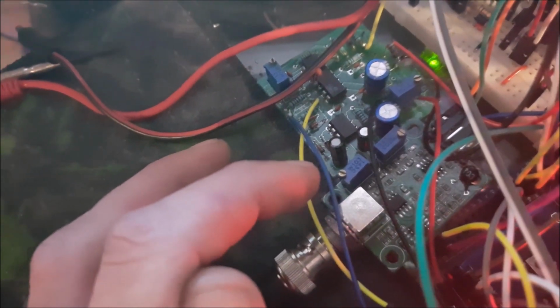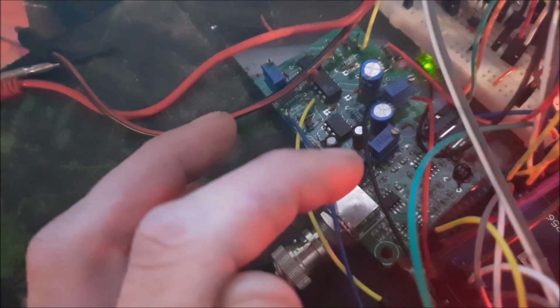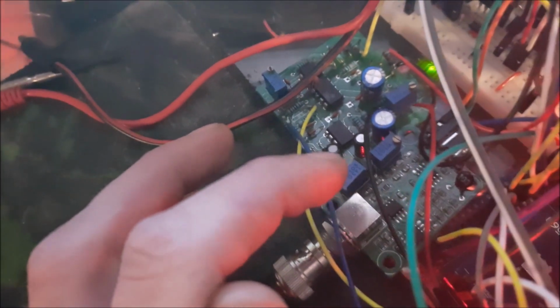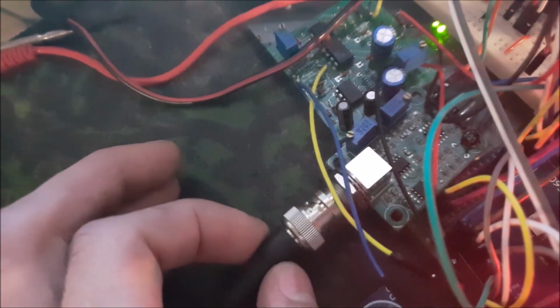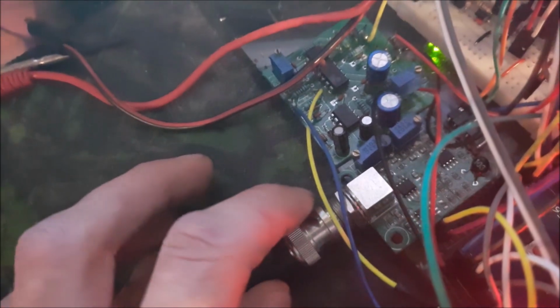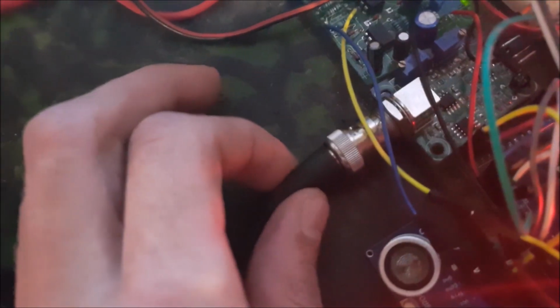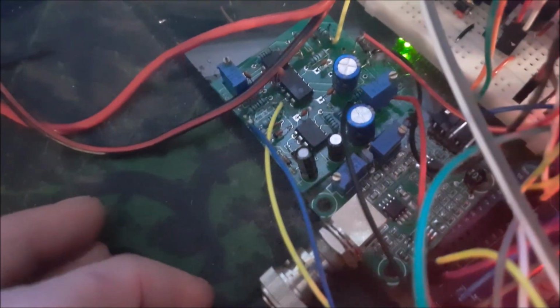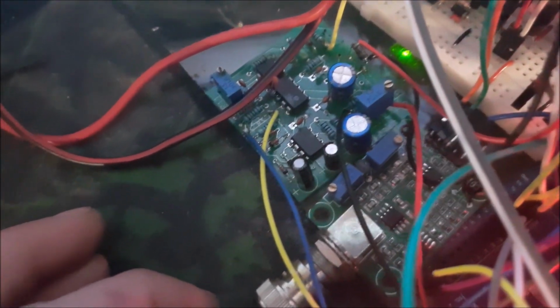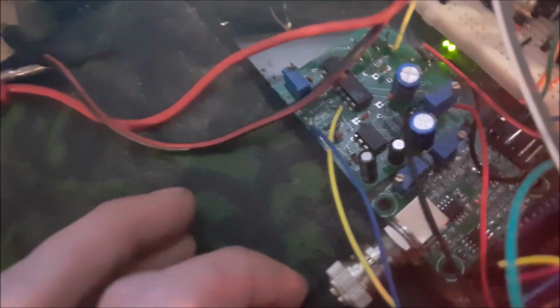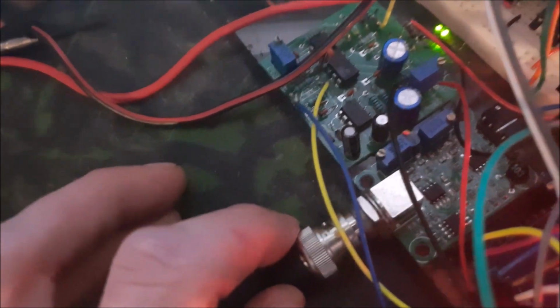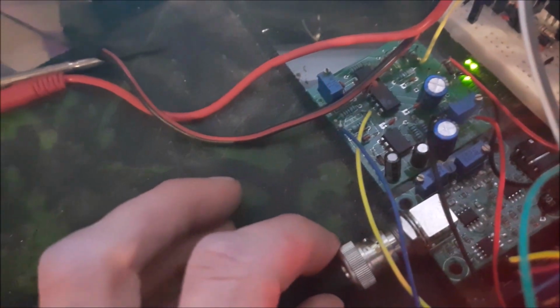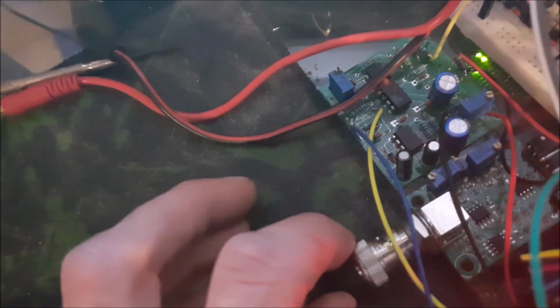Now, if you're thinking, well, that's only going to be putting voltage out to the sensor whilst I'm taking a reading. No, these sensors are always active. They're not solid state, but let's think of them like that, that there's always voltage and power supplied to each probe, and that you're essentially just taking the reading whenever you request it, because they're always ready for your request. So there is always power and earth being supplied to each one of these probes, and that will affect either of them, the power or the earth on its own.